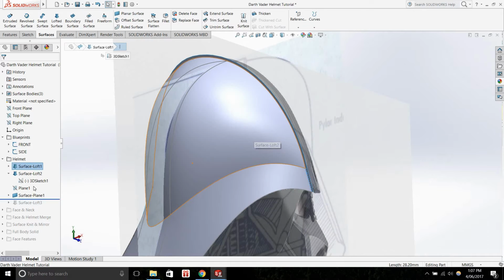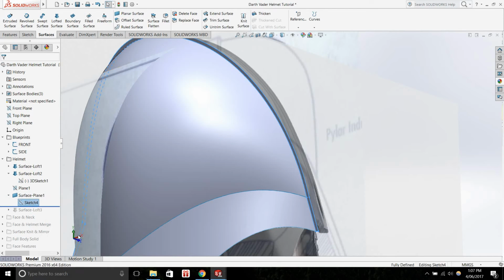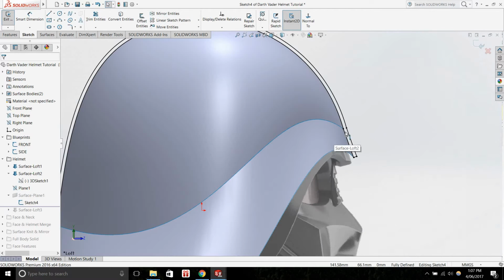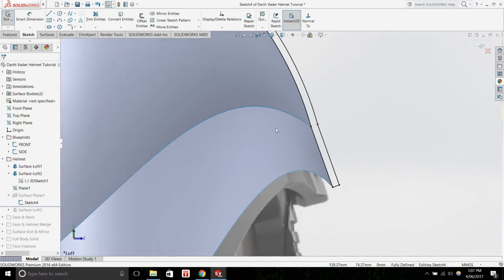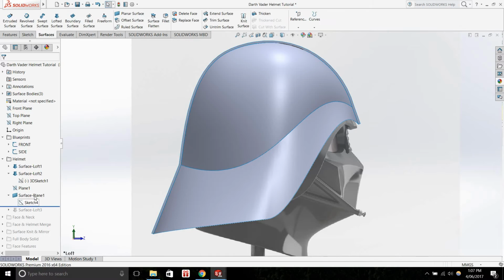So if I go back into my model, what I did is I created a plane, then I created another sketch, which basically offsetted that edge, so that when I create a surface there, it creates that first rib. For that, I used a different tool, the surface plane tool, which is great if you're just trying to create a flat surface on a defined plane. You can generally have any enclosing boundary to create that.